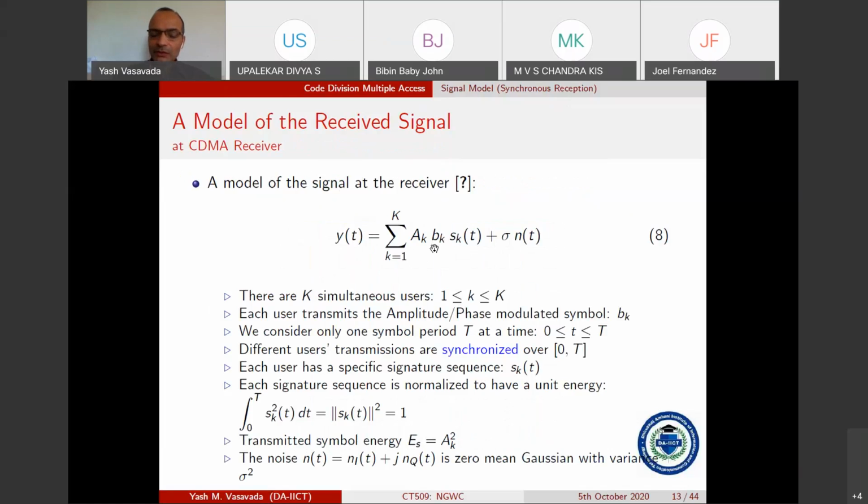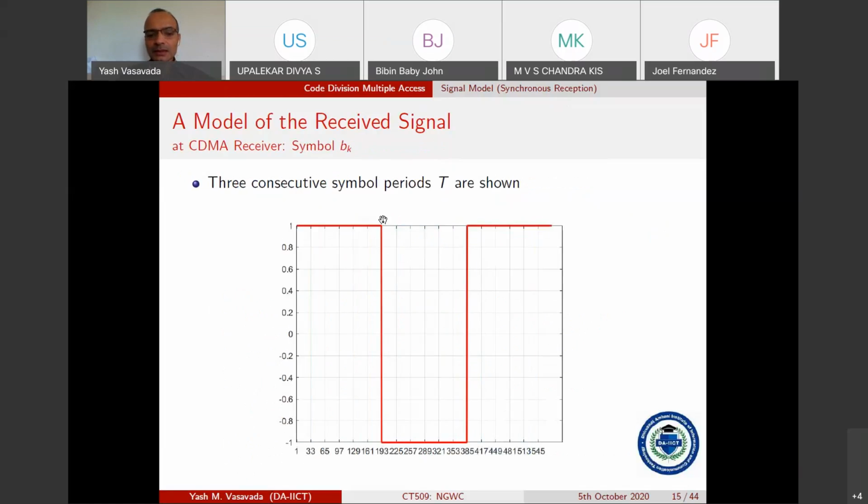And so if I wanted to plot just B of k here, what will be the y-axis? In order to make this symbol have unit energy, the y-axis will have to be, I just said it a moment ago, 1 over 192, except, sorry, I think I made a mistake. It should be square root of 1 over 192, because this is voltage, not power.